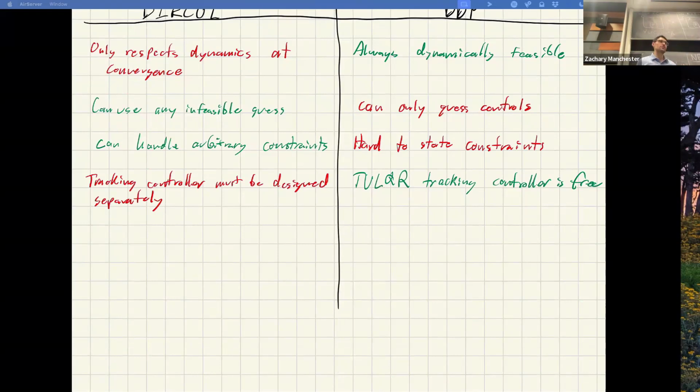There's lots of ways to get around that. A very common thing to do in that context, if you care, is to basically regularize. With these kind of online applications, you're always warm starting, right? So you'll solve it, and then 10 milliseconds later, you're going to warm start it off the last solution. You're going to time shift it 10 milliseconds and solve again with a warm start. Doing that warm starting, it tends to not go too far away. But you're absolutely right. If you get knocked really hard, it might go really far away.